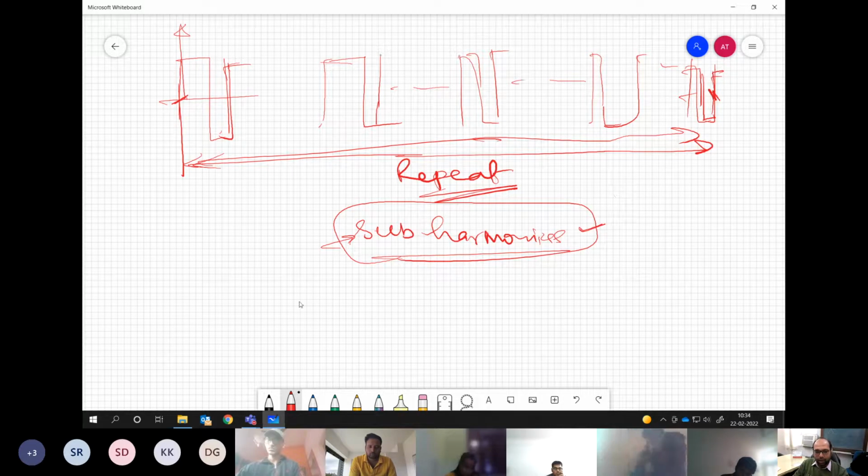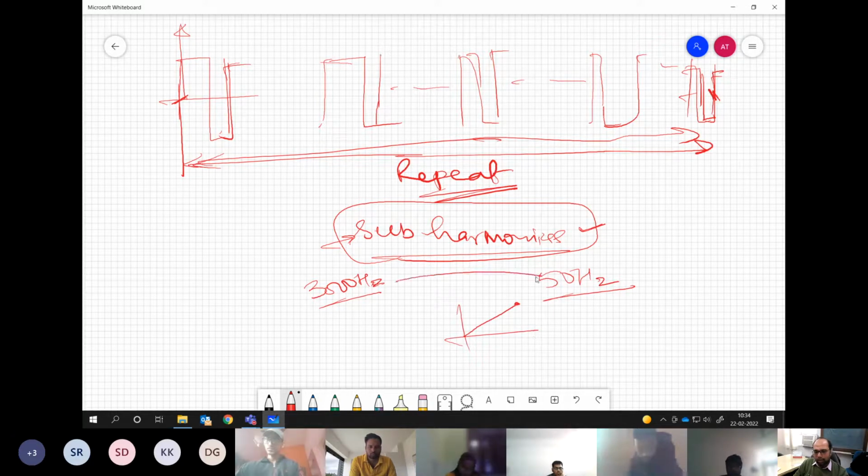Let's say you have a switching frequency of something like 3000 hertz and you are trying to run a 50 hertz motor. So what will happen? You will run the frequency all the way from 0 to 50, right? So some places it will match. The ratio will be some integer. Say for 30 hertz, for 20 hertz and all these things, it would be an integer. But some places it will not be. Say for 23 hertz, this will not be an integer number. The ratio between the two, right?